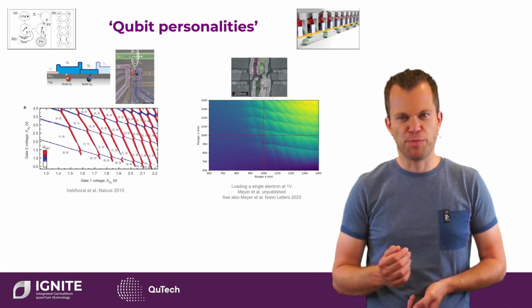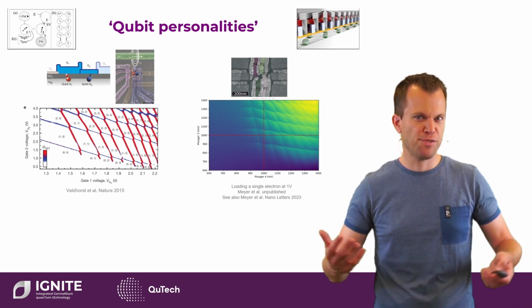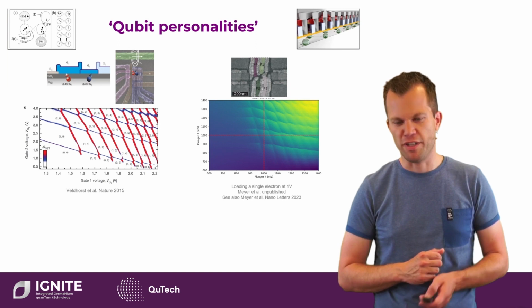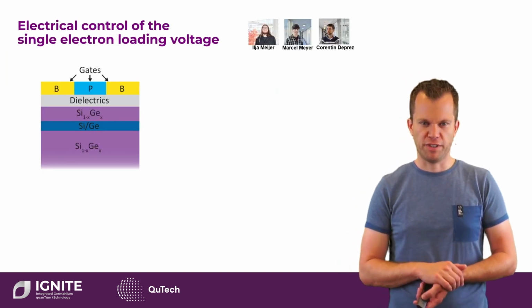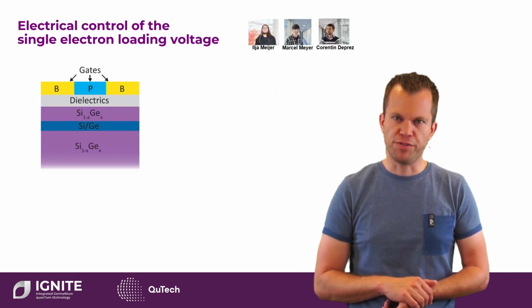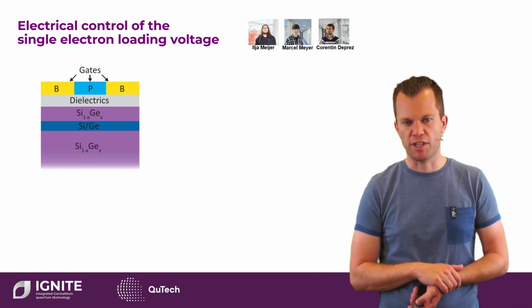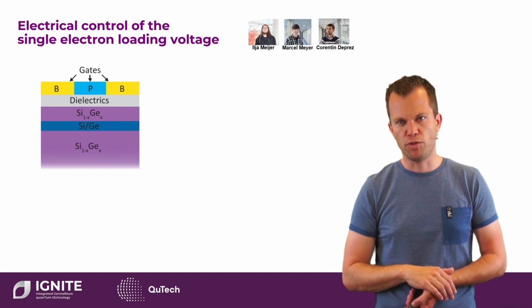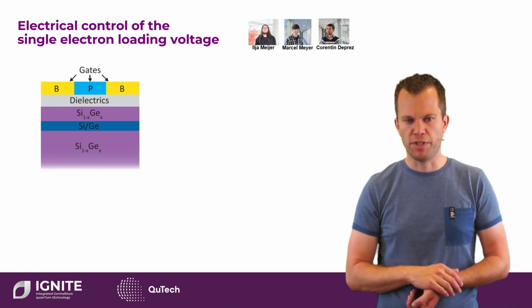So it seems that this is now possible today. How can we do this? Better materials? Well, we see that heterostructures offer more knobs. And I want to focus on that. So here you see an example of silicon. In germanium, it's rather the same. Both are heterostructures. There is a silicon or a germanium quantum well, where we define our quantum dots in.